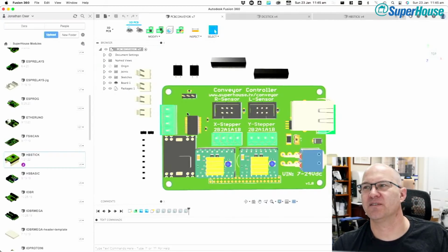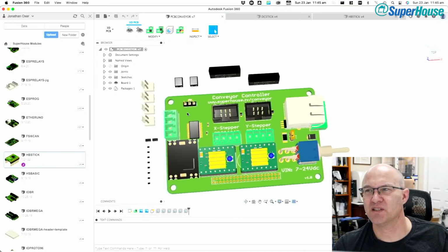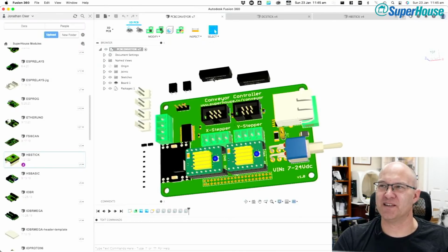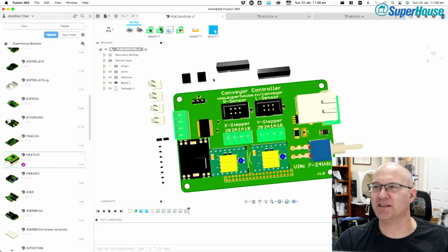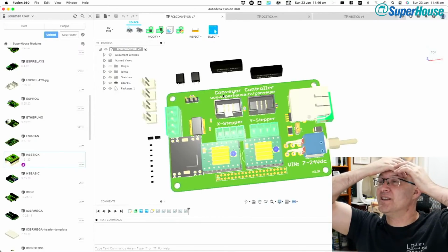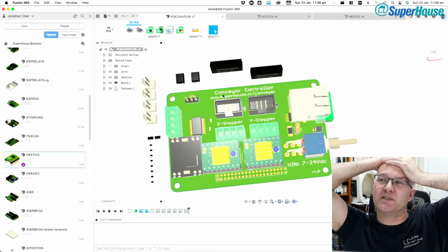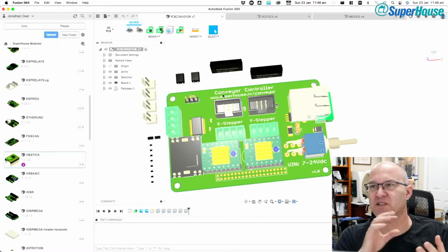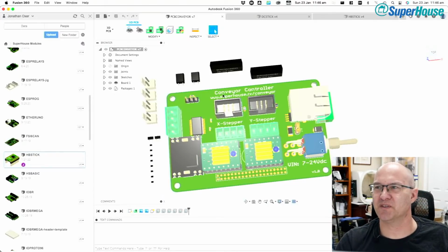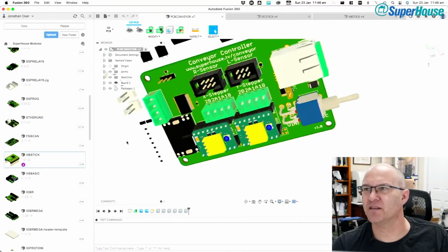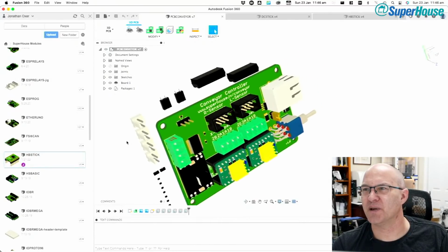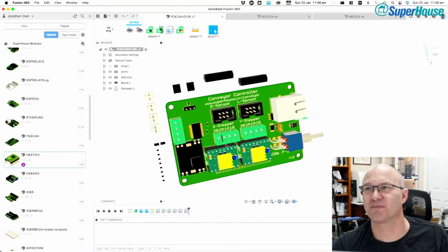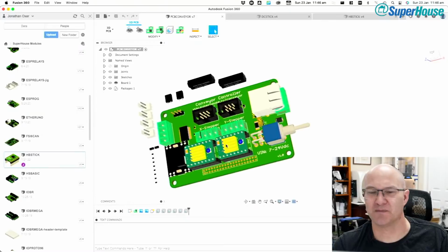The thing is that there are very few small parts on this board. It's mostly just big connectors and other stuff, like the switch and relays, which are huge. It's all just stuff that gets in the way. When this design is done, it's going to be a relatively simple board in terms of the surface mount parts. The surface mount parts are going to be just a few, squashed in around all of these massive connectors. Maybe I could go for smaller connectors, but then it's less convenient. My goal is to make it all fit. I shall see.